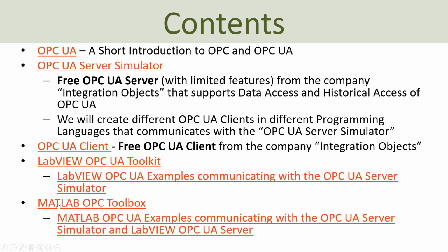Finally, I will do the same within the Matlab programming environment. And in Matlab we have the Matlab OPC Toolbox. And this toolbox supports both classic OPC but also OPC UA. So we will use this toolbox to create some examples that communicate with this OPC UA Server Simulator, both for writing and reading data.